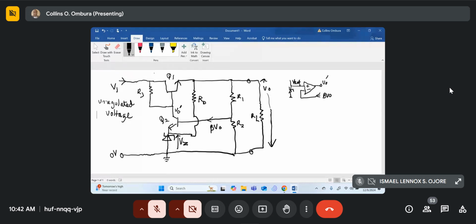I'll mention most of our lab power supplies, all our old lab power supplies, apart from those new ones that they brought, are using this circuit. Of course, the ratio R1 and R2, and now we change it to a pot. So you can slide it up or down to increase the voltage. And you can use two of them to have a positive, negative power supply. So for the bottom supply, you can use PNP transistors. Or you can just use the same circuit, but you use two of them. So the top of one of these ones will be your zero reference.